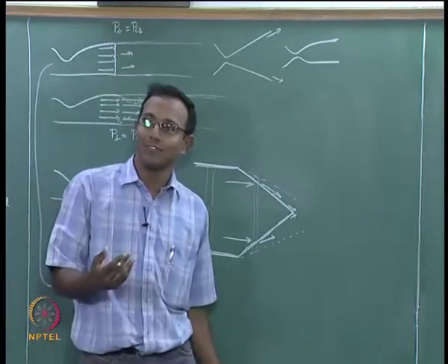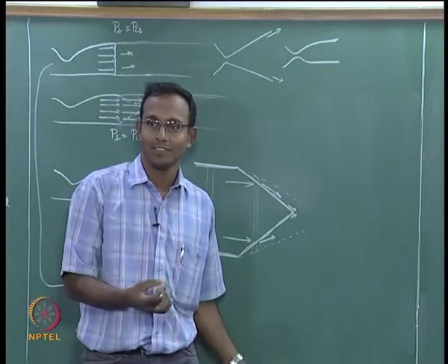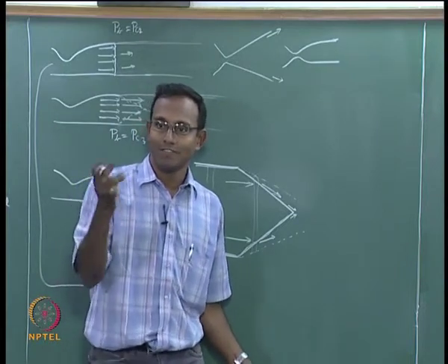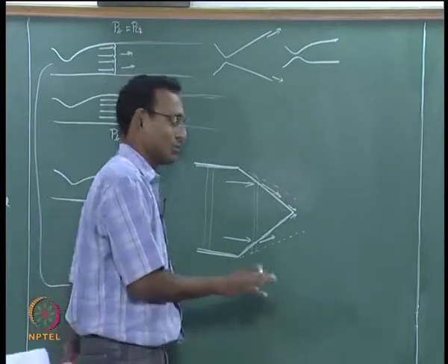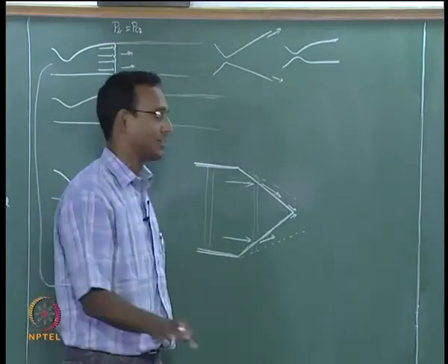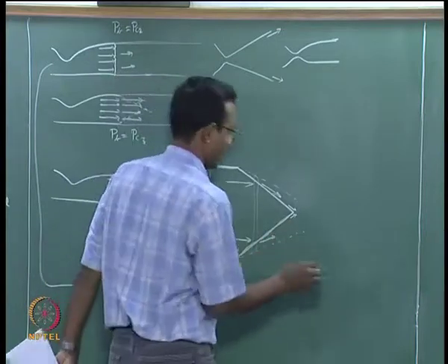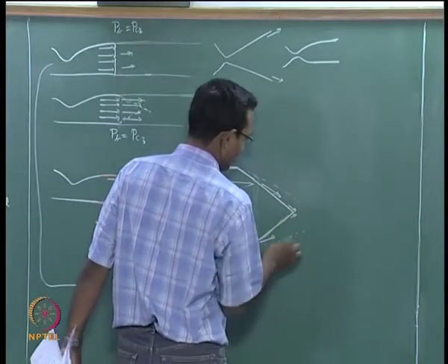What should I satisfy downstream of the point? Pressure and velocity direction, two conditions, always those two conditions. In supersonic flow typically these are the only boundary conditions, pressure and velocity direction. Okay. So now I have to think about